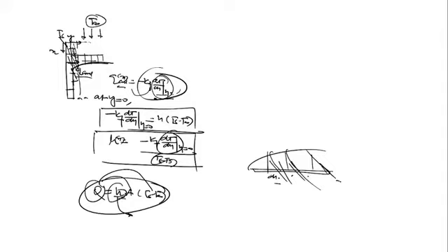Can you imagine, if the fluid flows over a flat plate, how will you calculate the temperature distribution? Is it a very simple thing? To find the temperature distribution, you can do one experiment: place thermocouples at different distances from the wall, say at 1 millimeter, 4, 6, 8 millimeters. With the fluid flowing, the thermocouples measure different temperatures, and through that you can find the temperature profile, how the temperature varies with y.